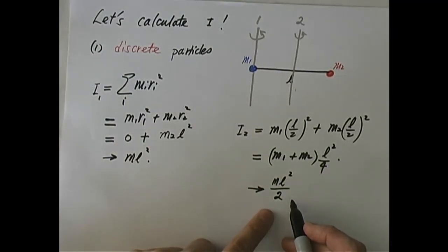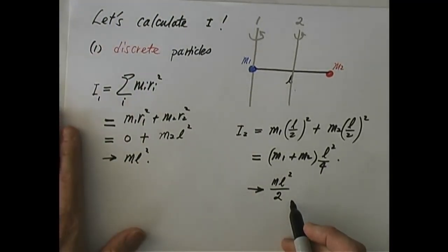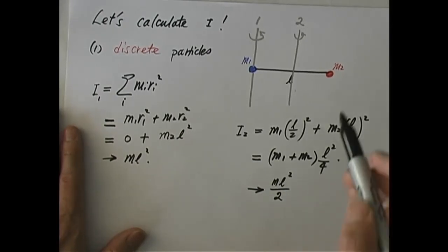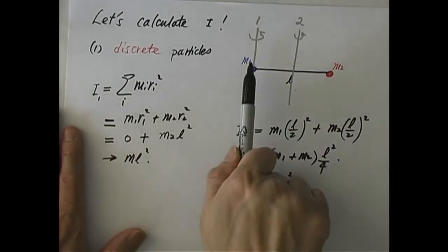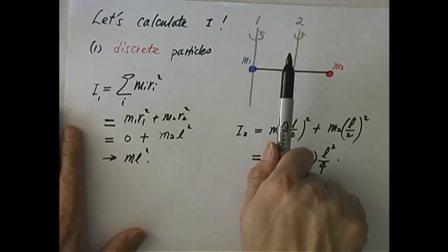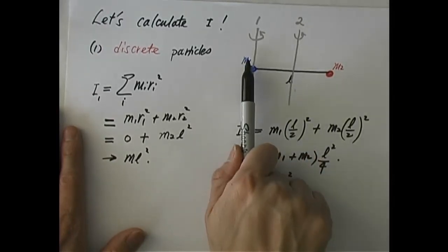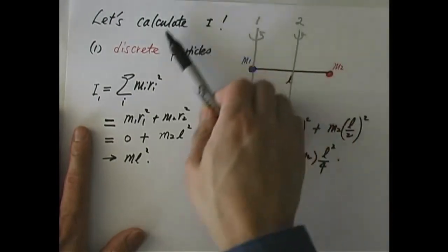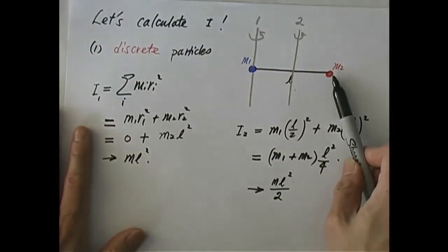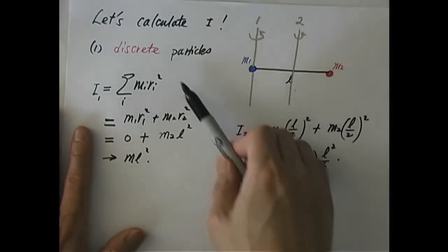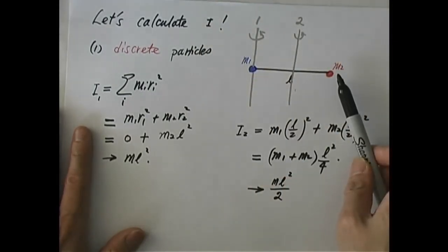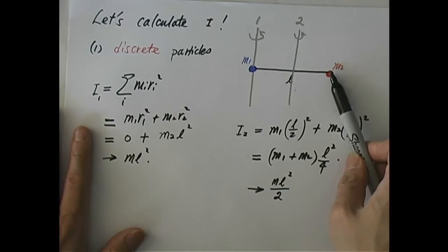Why is that? Well, in general, when you look at an axis pretty far from the center, like about one edge, then as the thing turns around, this mass is pretty far from the axis. Therefore, for the same angular speed, it has a large arm, which means its linear speed is large, which means you get greater rotational inertia.